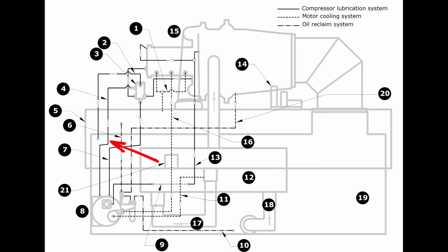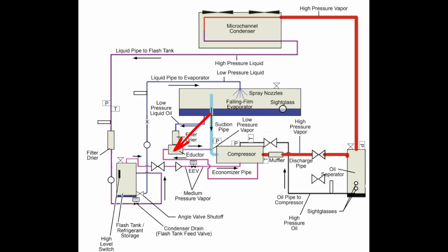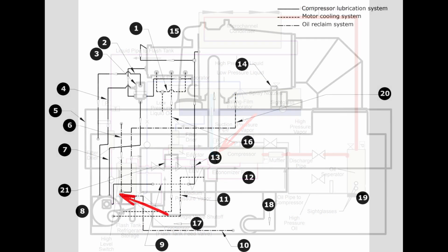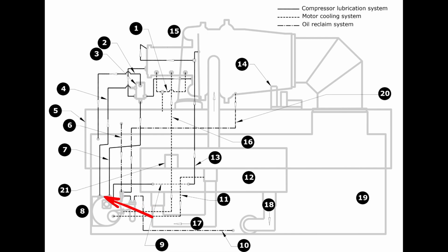Or I say somewhere else. It just gets that vapor pressure drawn off so that we don't allow too much of it to stack in here, which is going to inhibit our ability to not only move the oil, but also to get the oil recovery process to work properly. And that's where with our YVAA style, this wasn't an issue because we recovered back to our suction line, so the compressor was constantly pulling on this. But when we move into a tank design like this, we need the ability to pull that vapor off and have a vent somewhere, so that we don't cause that vapor to stack and build refrigerant pressure in here that we don't want to be there.